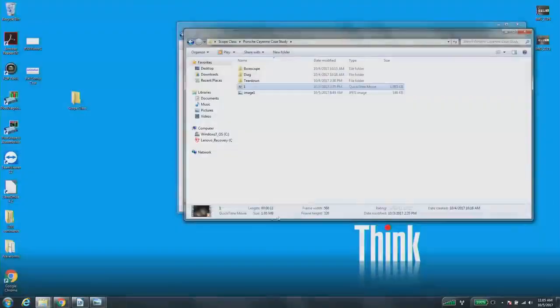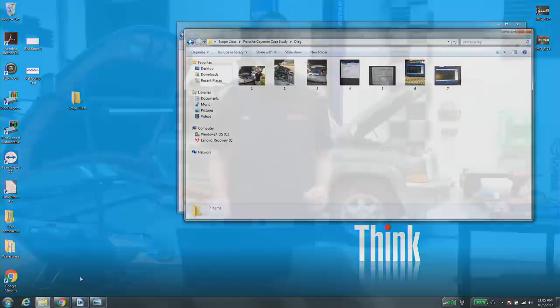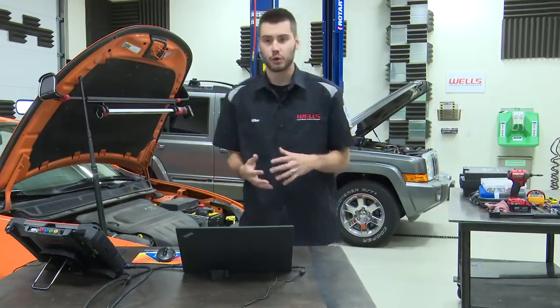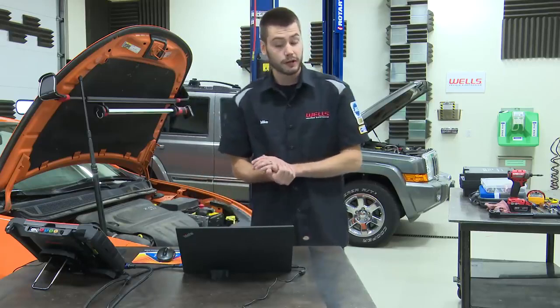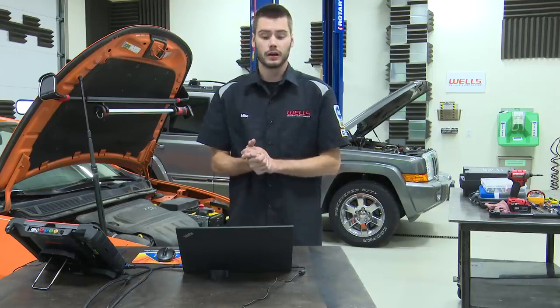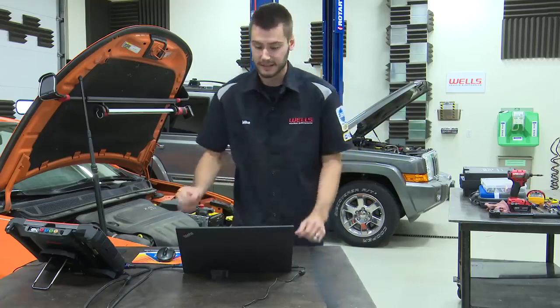So that sounds lovely. This thing was throwing a consistent P0018 code. Now, if you guys watched our Toyota class, we were dealing with cam crank correlation codes on that Toyota, what was that, a 4Runner? So a P0018 is also a Bank 2 cam correlation code for this Porsche. So he was applying some of the lessons that he learned in that class to this vehicle.